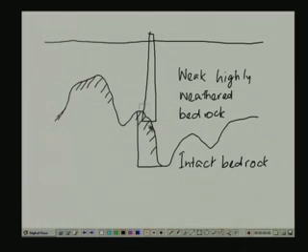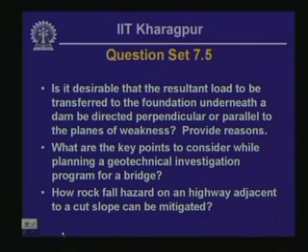We need to bear the pier at a deeper elevation, like that, in order to ensure stability. So we need to be worried about the local variability of the load bearing stratum in terms of the elevation differences in case of a bridge foundation.